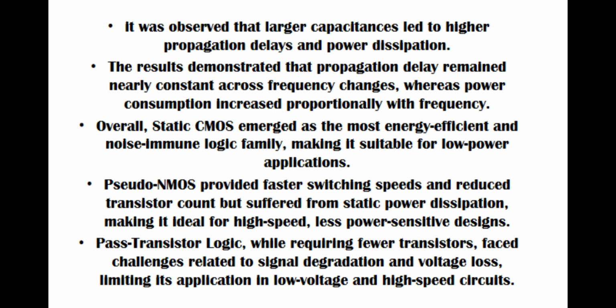Last is the pass transistor logic. While requiring fewer transistors, it faced challenges related to signal degradation and voltage loss, limiting its application in low voltage and high-speed circuits.